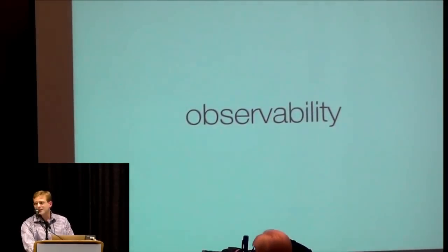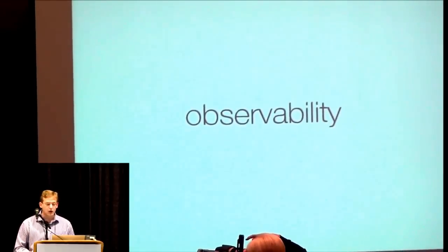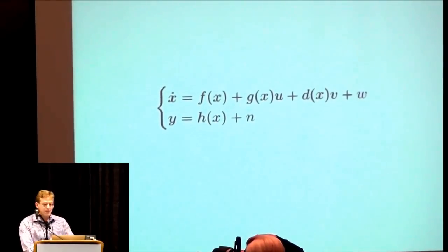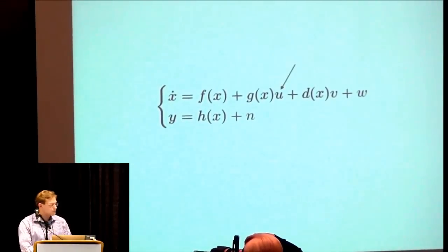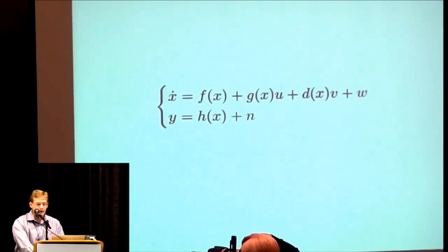Observability is a necessary condition for any algorithm to infer the true pose states in a dynamical model of a sensor platform. Absent observability, there could be infinitely many trajectories x that are indistinguishable given visual measurements y and inertial measurements u. It's a structural property of the model, and it does not depend on noise, which by assumption is uninformative of the state and can be assumed absent.